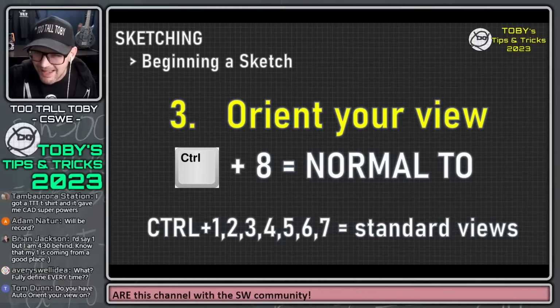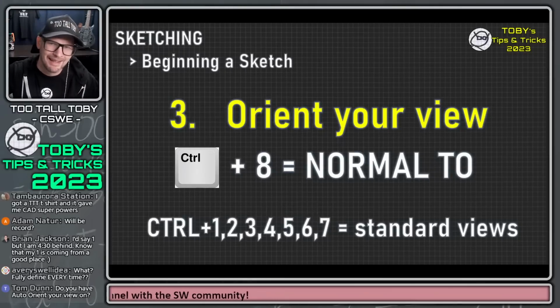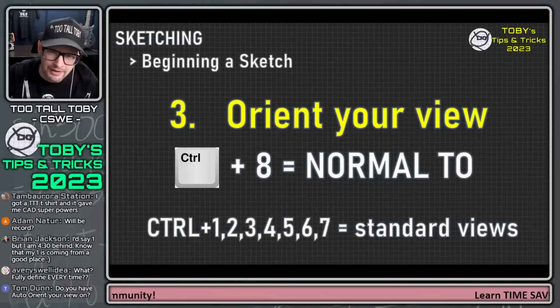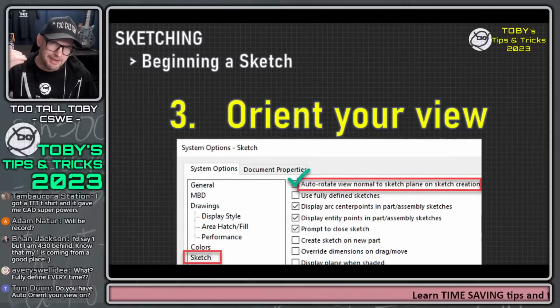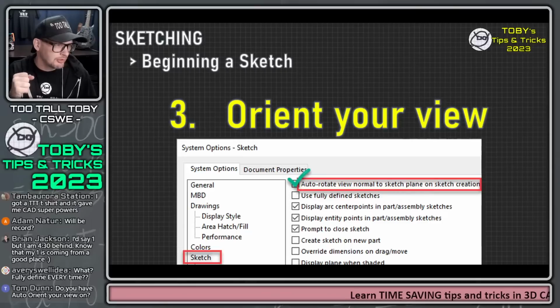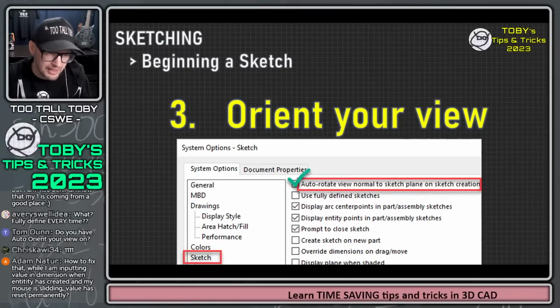Amos in the chat is saying, what? Fully defined every time? Don't worry, bro. We'll get there. We're going to talk about that in just a little bit as well. And Tom Dunn in the chat says, do you have auto orient your view turned on? Great question, Tom. And so what Tom is referring to here is that there is an option in the beginning of your sketch. When you go to begin a sketch, in your system options under sketch, there is an option for rotate view normal to on sketch creation.